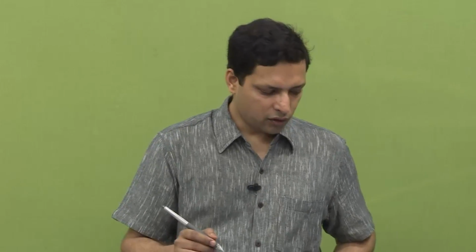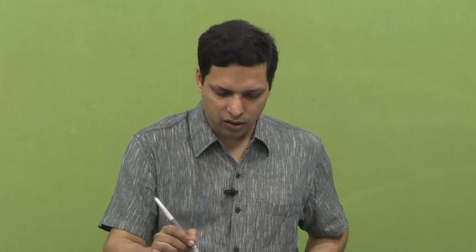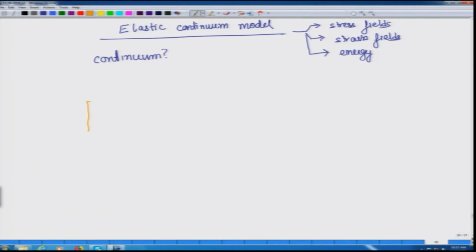So, now having said that, what are the stress and strain? How do we define stress and strain in a system like this? Stress and strain, as you would know, are not a vector or a scalar quantity, they are a tensor quantity. So, it has 9 different components. If we look at a small element of the material in a cubic form, let us say we are taking an x, y and z coordinate system.